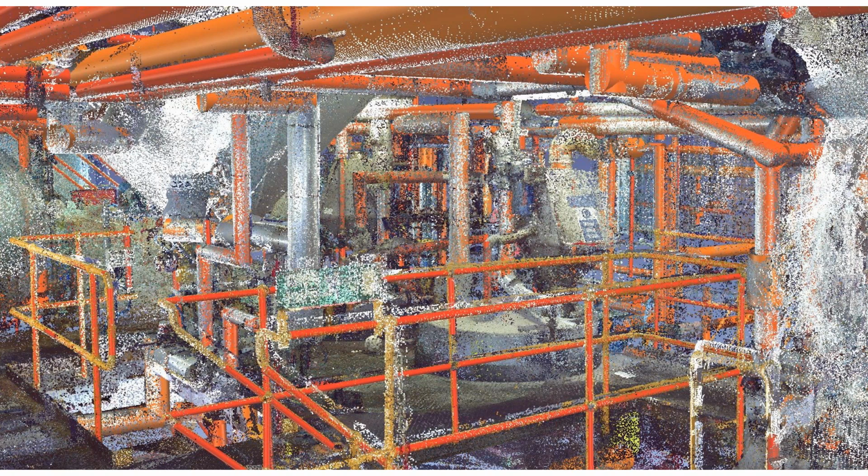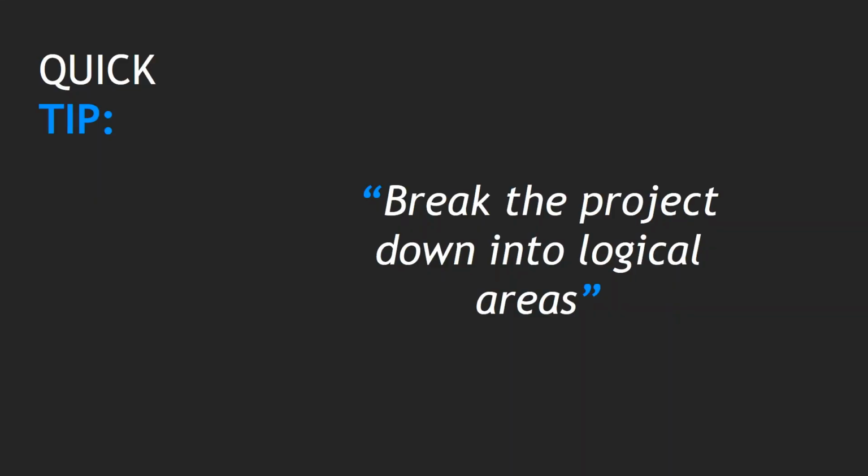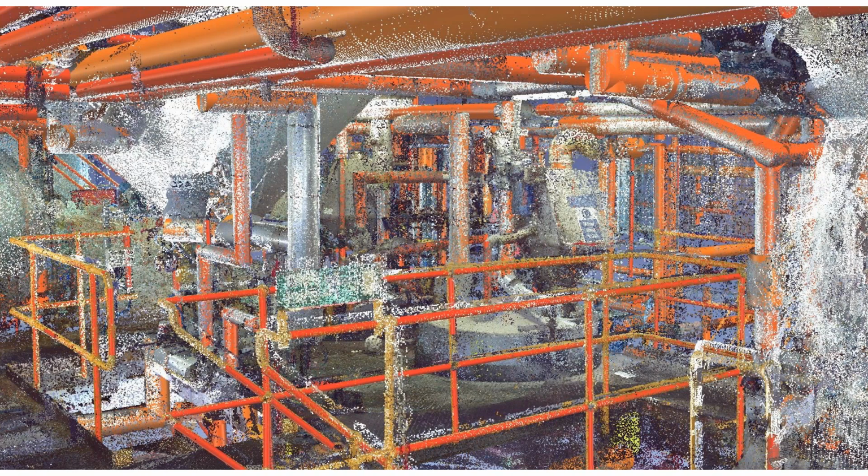What you're looking at here, though, is the point cloud data within Edgewise, the ClearEdge Edgewise plant software. And the orange 3D vectors that you're looking at is actually all the pipe work that Edgewise found automatically. So at this point, we have done nothing. All we've done is literally put the point cloud data into it, allowed it to run overnight, and come in the next morning, and this is the sort of image we'll be looking at. So it picked up on something like 80% of the pipe work, I believe it was. We've still got to go through a couple of steps of adding elbows and T's, but again, a lot of that is automated.